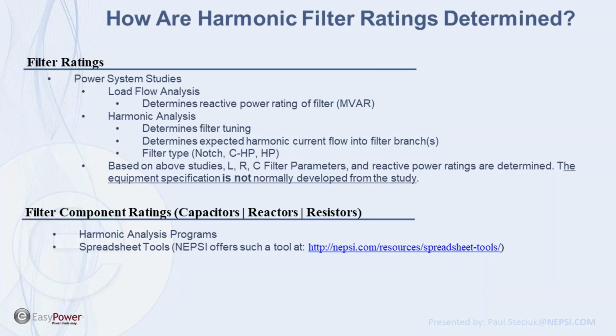And in the end, in the specification, you specify 100% to the reactor supplier, the capacitor supplier, or the harmonic filter supplier. You make an assumption that, well, it could be 100%. In so doing, you've created a bulletproof design. You've created a filter that will never fail because you've designed for the worst case condition at 50%. You still have another factor of 50% of margin to take care of things that you have not accounted for.